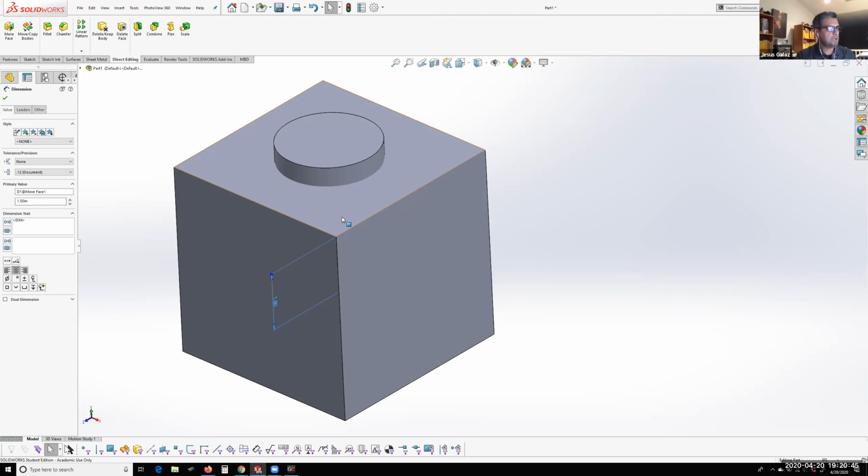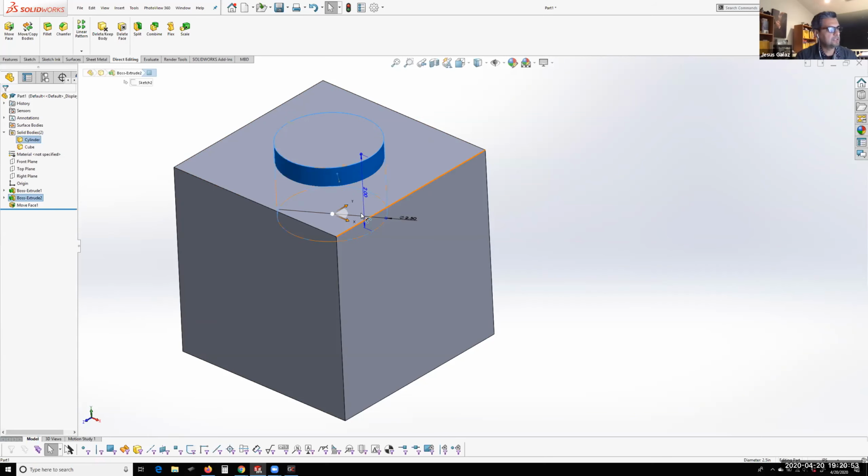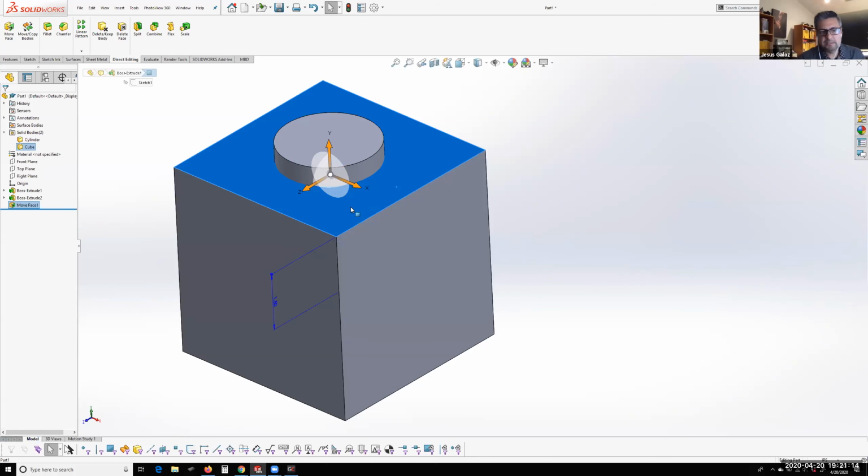Now this is back to a 5x5 cube, and you're asking, what about the cylinder? It should be up above here. Because it is a separate body, it didn't follow the moving up of that piece, since that's a separate operation. This got edited after the fact, so it is no longer tied in with that cylinder sketch and the cylinder extruded from that face.